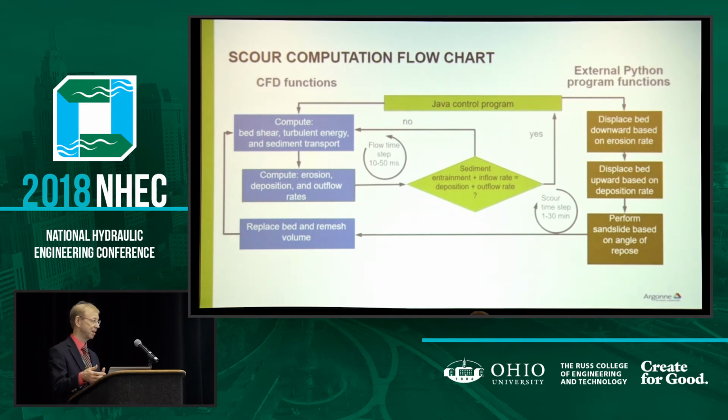Then we displace the bed upward based on the deposition rates. Then we perform a sand slide algorithm based on the angle of repose. Then we've got a deformed bed. We export that. Then we go back over to the CFD side. We re-volume mesh a slightly changed bed, and we start that up from the previous solution.